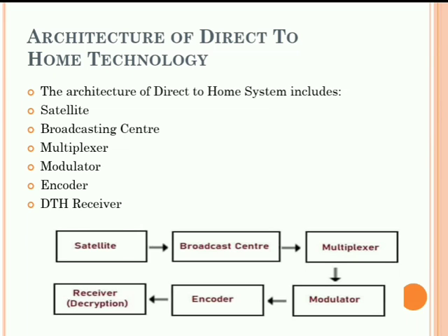After that, there is a DTH receiver. The DTH receiver is the end component in the entire DTH system. This DTH receiver decodes and descrambles the encrypted signal. For unlocking the signal, it needs the proper decoder chip for the programming packages. The service provider can communicate with the chip with the help of the satellite signal to make the required operation to decode that particular program.